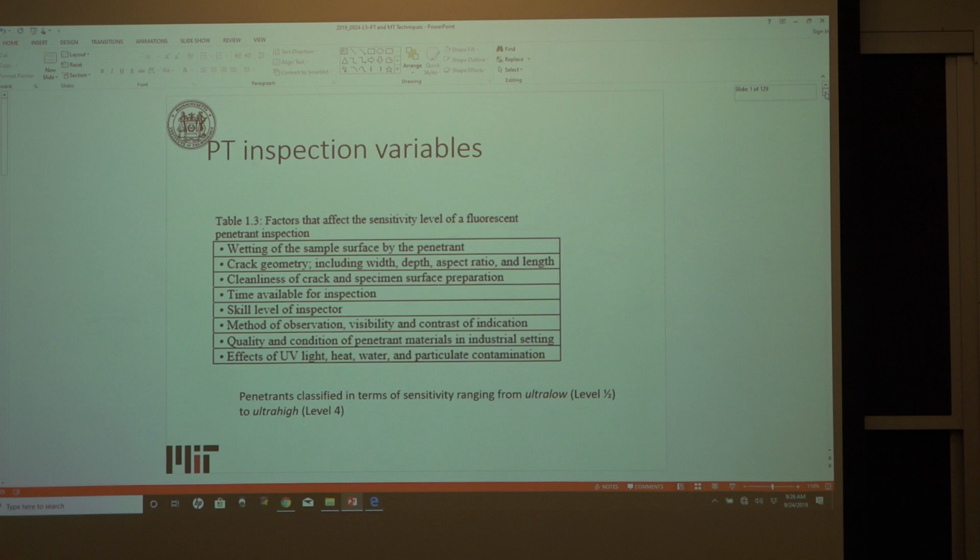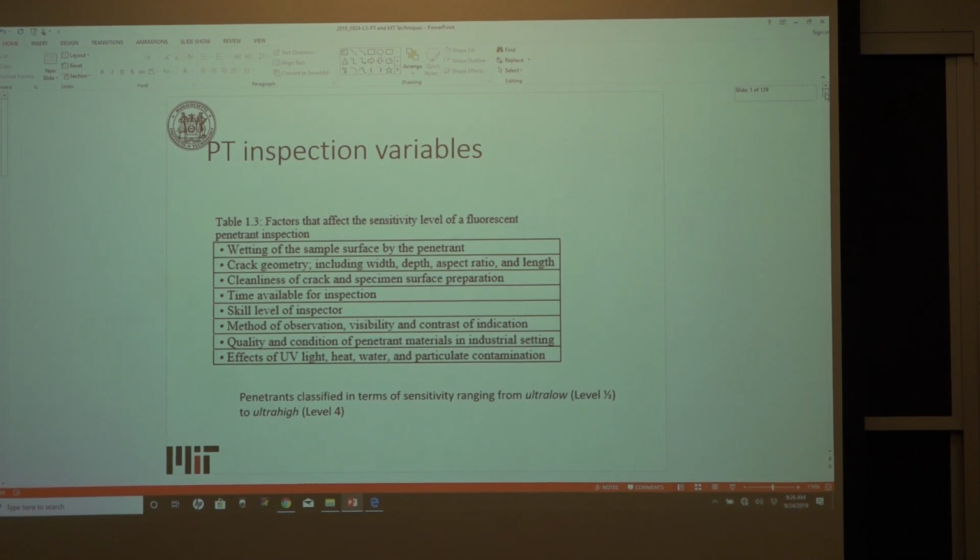That does involve some type of grinding sometimes, and if you're not allowed to grind the sample down to get a lustrous surface, then you have to start looking at other techniques. That's when you decide if you use an eddy current or ultrasonic technique instead.